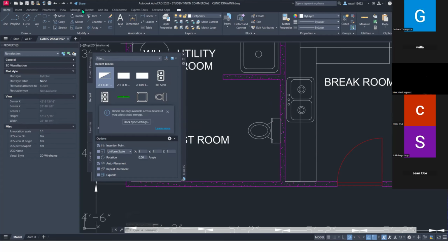All right. So what we did is we did the reversal of a block just to show you how it was made. So that's what explode does, right? Exactly. If you build a block and then you want to edit it later, you can explode the block, redo it, and reblock it together. Call it something else. Delete the other one. Whatever you want to do.